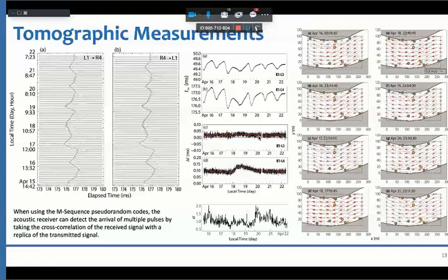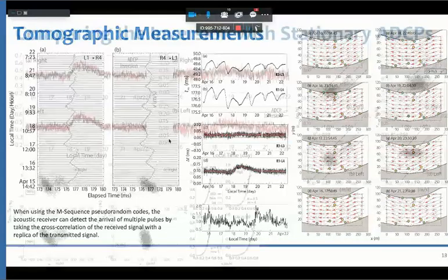If you remember, we had to have an angle between the acoustic path and the flow velocity that is smaller than 90 degrees. It is very close to 90 degrees, which means that you're going to resolve a very, very small component of velocity. As a result, you don't see a lot of influence of the flow speed changes on this one.